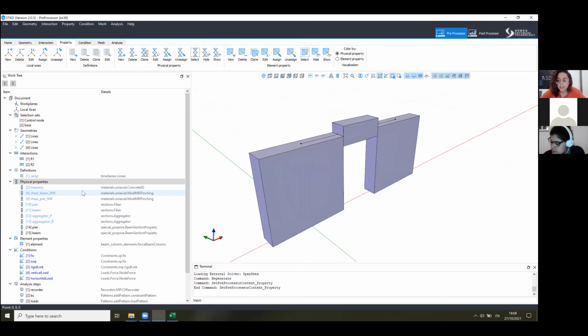We already discussed this for RC structures in detail. Let's say the idea is the same. Here we have the example with the distributed approach. Axial and bending stiffness are distributed along the length of the element, and the same goes for shear. In this case, in order to include shear, we had to add something called an aggregator. I think we already talked about this, but let's start from scratch.